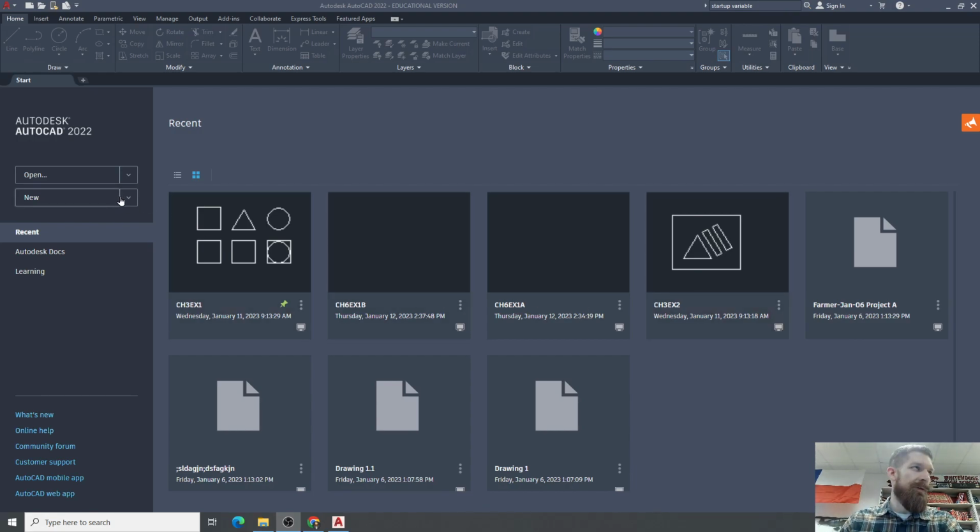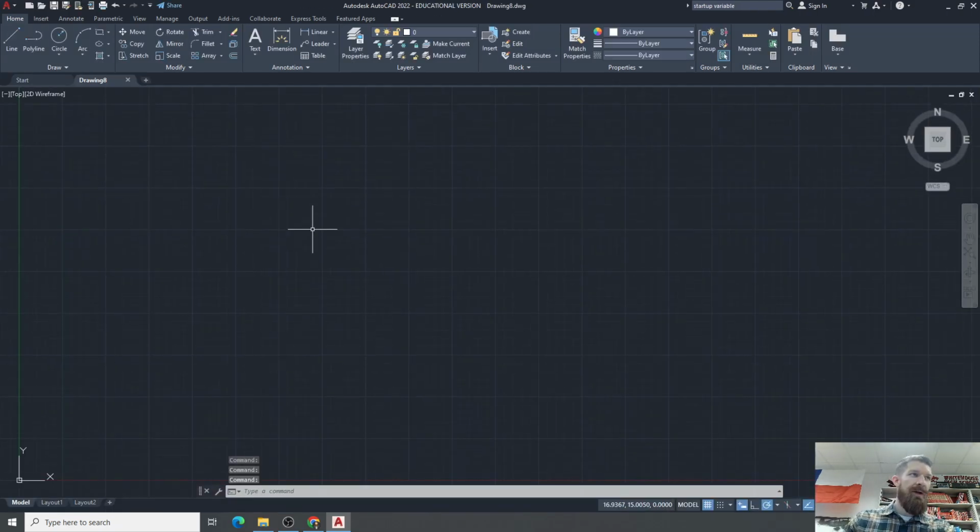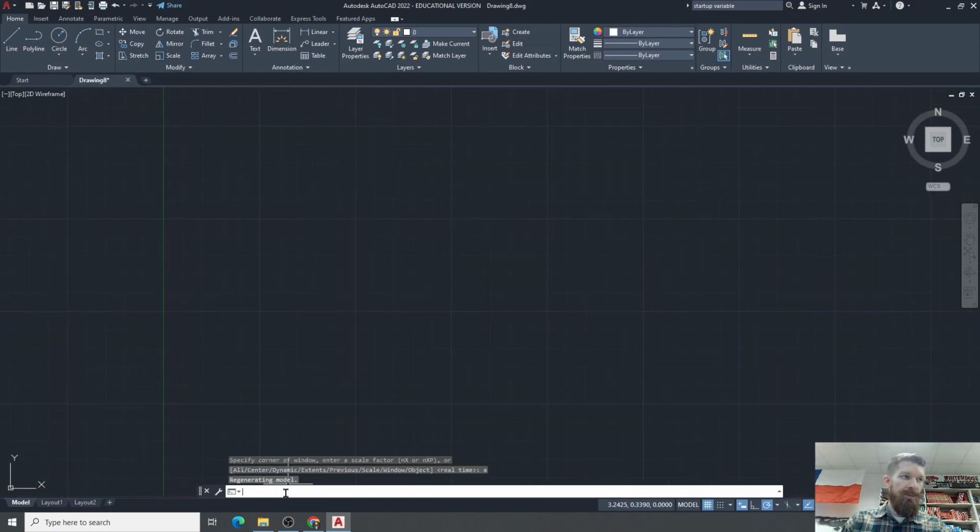Let's get started here. I'm going to open up a drawing template. Remember, AutoCAD is inches. AutoCAD ISO is millimeters. I'll use inches today. And then in keeping with good practice, let's set our limits. I'm going to set my limits to bottom left-hand corner 0,0, top right-hand corner 17,11. Why not, right? And then zoom all. Great. I've got my workspace in front of me. I know everything's ready to go. Make sure you get in the habit of doing that when you start working, okay?